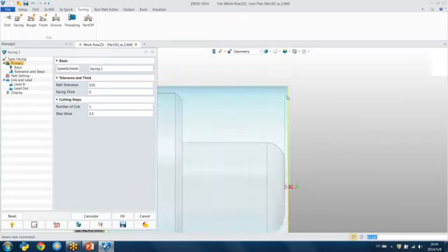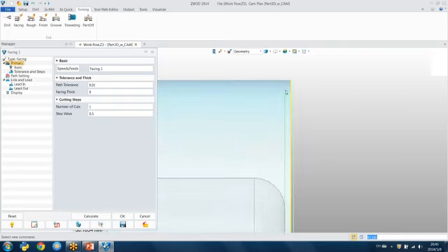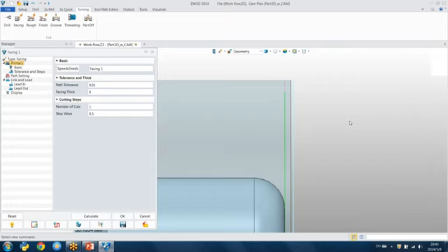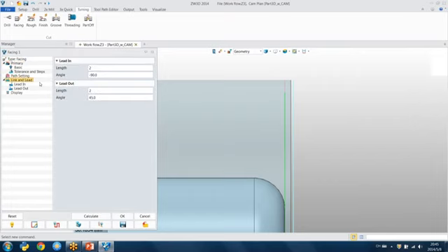With the toolpath, you can find actually the lead in and lead out is a little short. So I need to change the value. So I can use the lead in and lead out. I can change the length. Okay. So for example 45. You can find it's changed longer.